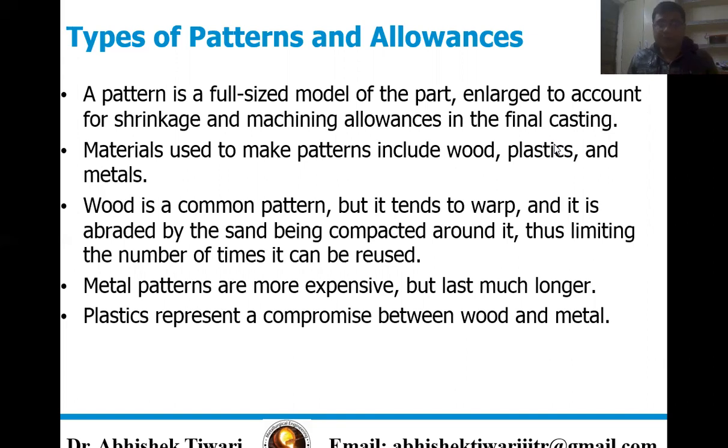Materials used to make patterns include wood, plastics, and metals. Wood is a common pattern material, but it tends to warp. So it can be subjected to warping, which is not good for a pattern.